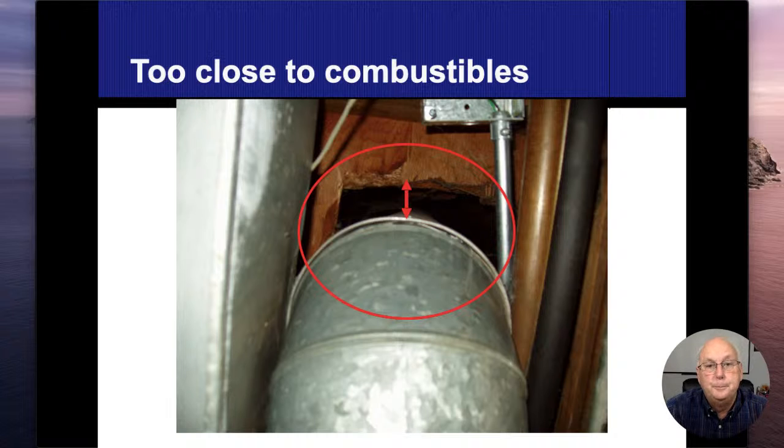And I get it, and I've seen the same thing with my own eyes. Something's been there for 15 years. You would think I would have some sort of melting and burning, just like I described, that we see, and sometimes it doesn't happen when it's there. I get it. But those distances are not there for when the furnace is operating normal. They're there when something goes haywire.